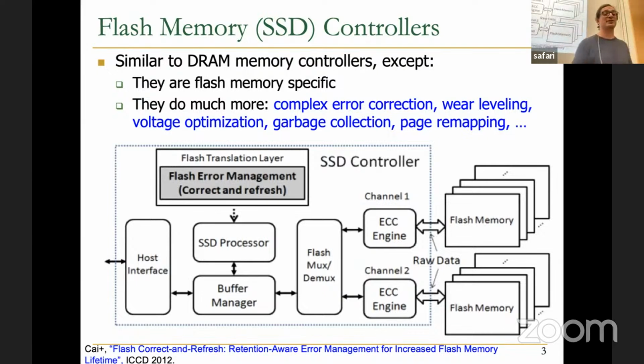So there are a lot of tasks over here, as you can see. For that reason, this SSD controller usually has hardware components that are specialized to do particular things like ECC, for example. There's hardware level ECC over here, also scheduling, etc. But it also has software components to do some other things like wear out management, garbage collection, etc. So there's a full processor that exists in SSD controllers today. In some SSDs, actually, you have 8 different cores over there trying to manage this memory.